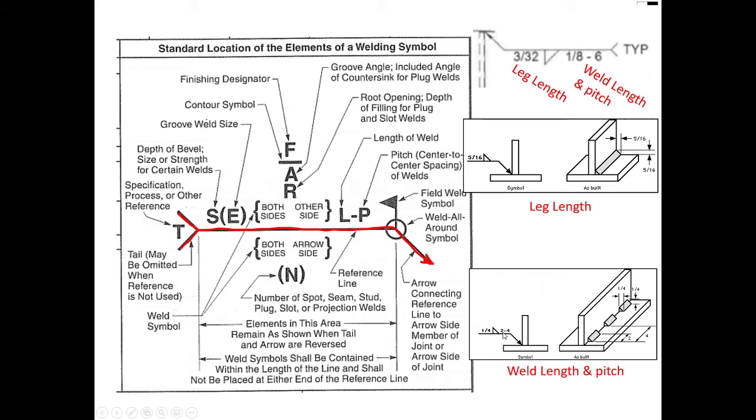So here, this is a 2-4, so that's a 2-inch length of weld, and then 4 inches center to center. So there's a 2-inch long weld, and then it is 4 inches from the center to center or from the edge to edge, either way, till you get to the next weld. Now, why do you weld in little sections like this? You often do that because welding imparts so much heat to something that it will cause bad warping. And one way to reduce the warping is just to put in less heat by using small amounts of weld rather than an entire weld.